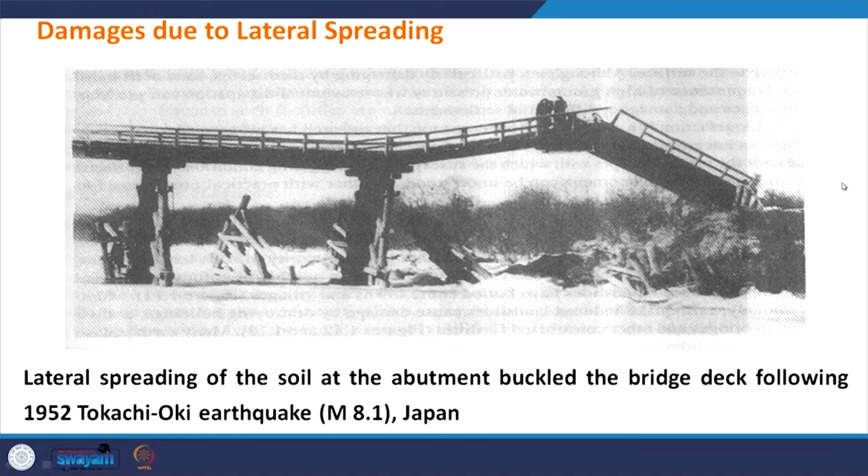So, this abutment got damaged. As a result, this abutment collapsed, then the deck of the bridge came down. So, this is also liquefaction induced failure of the foundation.